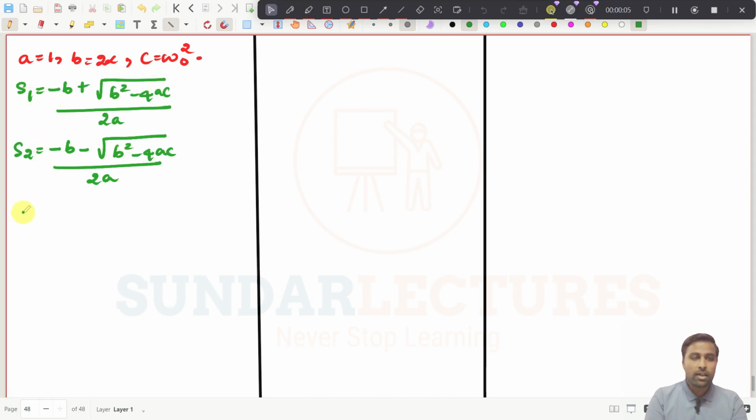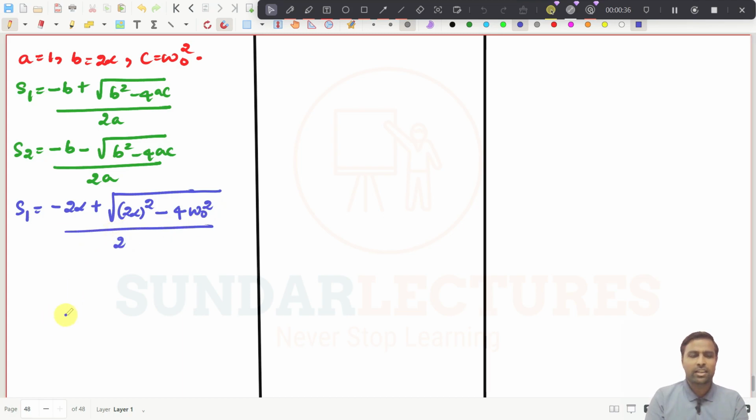What are the values? S1 is equal to minus B, so it will be minus 2 alpha, and then plus square root of B square, which will be 2 alpha the whole square, minus 4 into A, which is 1, so I don't need to put it here, and C is omega naught square, the whole divided by 2 into A, which is 2 into 1.